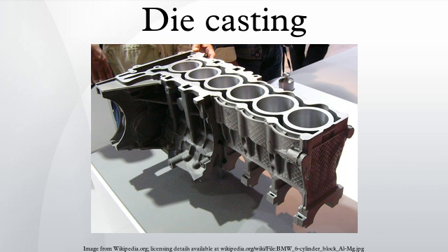Variants. Acrorad. Acrorad was a die casting process developed by General Motors in the late 1950s and 1960s. The name is an acronym for accurate, reliable, and dense. It was developed to combine a stable fill and directional solidification with the fast cycle times of the traditional die casting process. The process pioneered 4 breakthrough technologies for die casting: thermal analysis, flow and fill modeling, heat-treatable and high-integrity die castings, and indirect squeeze casting.